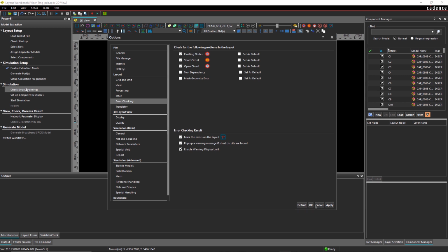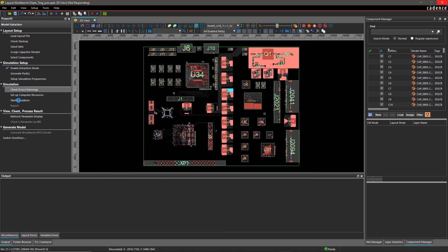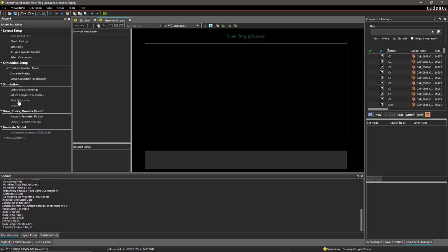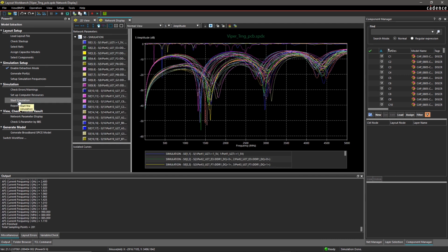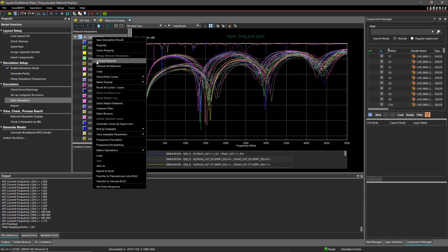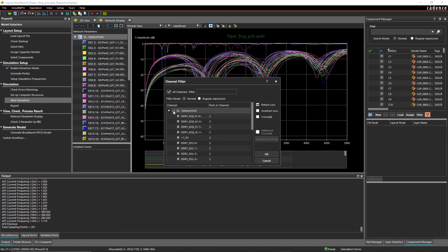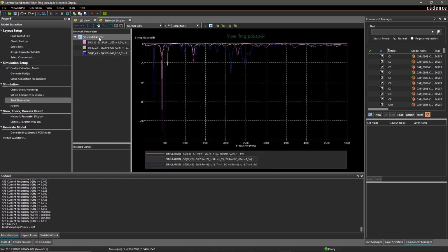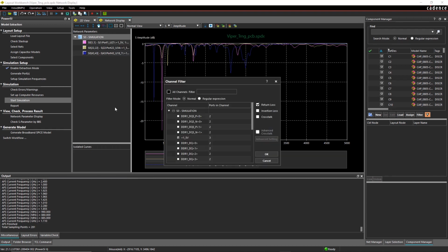Once the simulation completes, S-parameters are generated for each signal in the parallel bus interface. Easily review the return loss of the power plane. You can also review the insertion loss on the signals. The graphs for all the analyzed signals give you an accurate insight into the design performance for the selected areas.